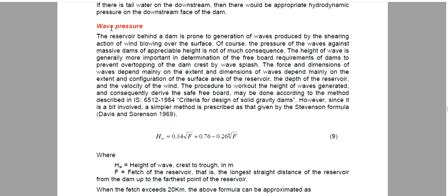But for dams of lower height and not massive, the height of wave is more important in determining the freeboard requirements of dams. Freeboard requirement is nothing but the difference between the top of the dam and the free reservoir level.